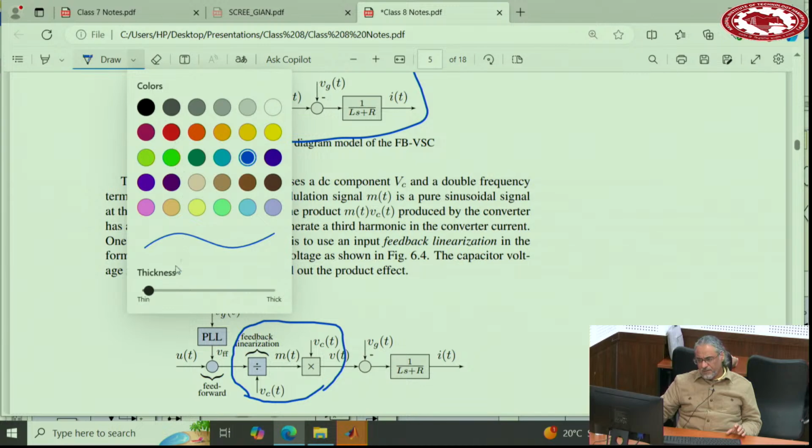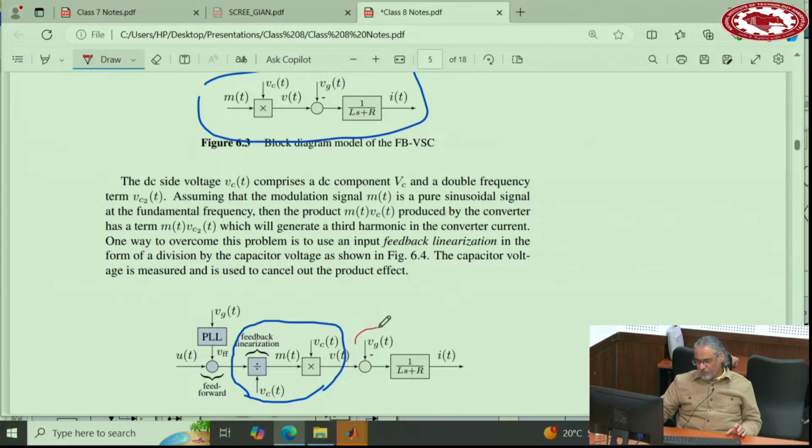And then, now this one also is an AC waveform added here. You can add a feed forward term for soft start and also for helping with the current limiting. That feed forward, if you use a filter like we said in DC, is not going to work here, because a filter will provide a phase shift, and that phase shift will cause a problem here.